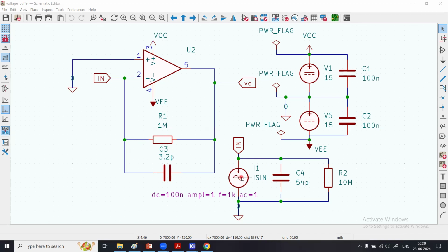Okay, so light is full on when there is no smoke, and there is a current. When there is smoke, beyond a certain threshold, the light intensity will decrease, and the photodiode current will also increase or decrease based on the principle of photoconduction. So this circuit together is an embedded application used in an industrial smoke detection system.